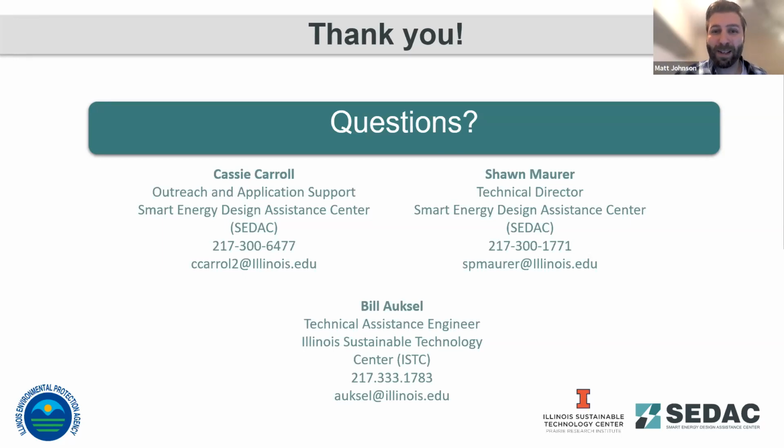Good ones are about 96, 97% efficient. You also have to make sure your motors are rated to work with the VFD because the output is mimicking that 3-phase AC current. It can add heat buildup to different motors, so you have to make sure the insulation in the motor windings is of the quality to resist damage from that added heat.